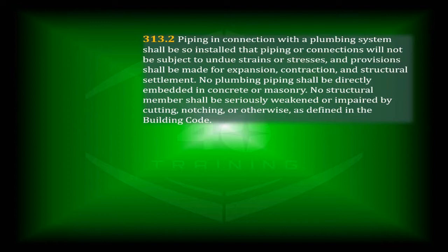Well, that's not a whole lot of hard stuff to remember there. Look, when we're talking about PVC, which we oftentimes are, PVC can expand a great deal in varying temperatures and situations. So you want to leave room for expansion and contraction if that applies to you.